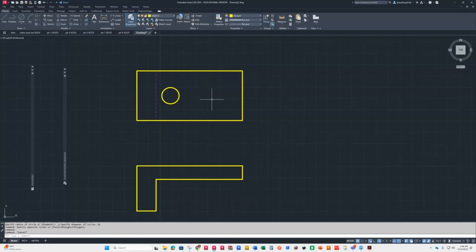And now I got another circle I got to find, which it looks like is 80 from over here. So like I said, you could offset over 80 like this. Except it can't, because that's not been exploded, right? See, I forgot to go in and explode that guy, so I'm going to explode him. So that's where, when you'd be like, hey, Mr. Doty, if you offset, it doesn't work.